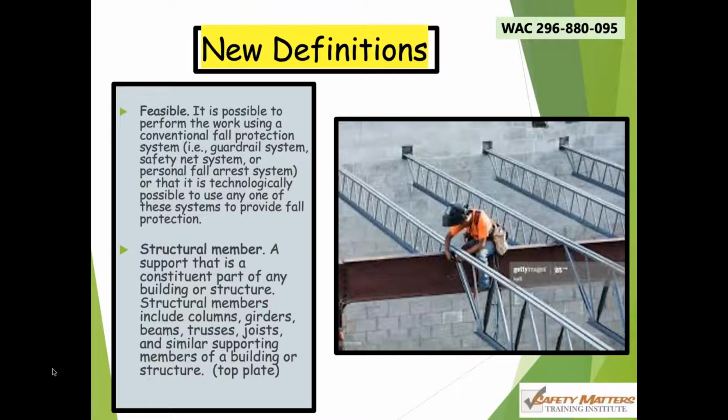What's the top plate? It's when I'm walking that little 3.5-inch 2x4 if we're in a wood building and we've stood all of the walls up, and I'm now walking on the wall, the top plate of that wall, as I lay down the floor, as I perform leading edge work.